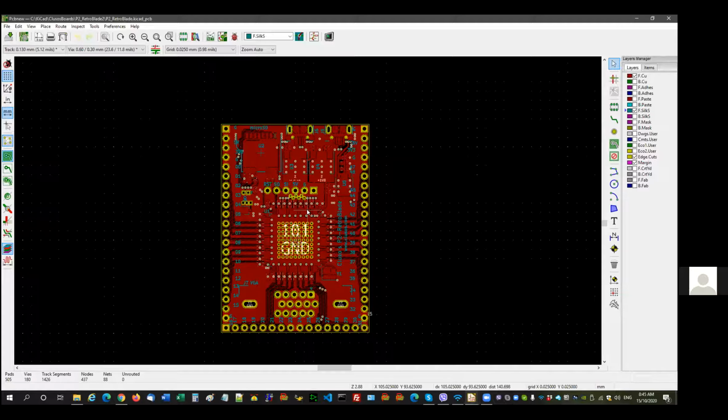And then to put the extra set of headers down the bottom and bring out another 16 pins, I thought made sense. And Peter suggested putting under the header. I tried putting RJ45s on. They worked. But then I came back to, well, if I extend it to 2.2, then I get my full 16 across. That means I've got to move each set of pins out 50 thou. So I extended the width of the board to 1.6. And I'm happy that this is a nice size board.